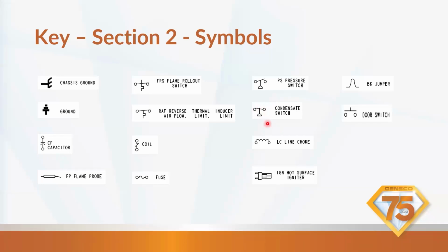It's going to drop open. So make sure you're paying attention that this is a normally closed switch. Under normal operations, closed, right? So that's a difference there. Some of these are open, some are closed, some close on a pressure rise, some close on a pressure fall. And that's what we're looking for here.